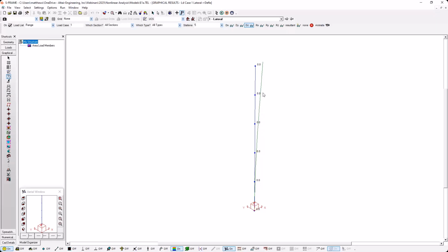We're basically just looking at the pre-analysis stress stiffness matrices and geometry matrices, and looking at what happens when you apply a static load to those with zero incremental updates to the analysis model.